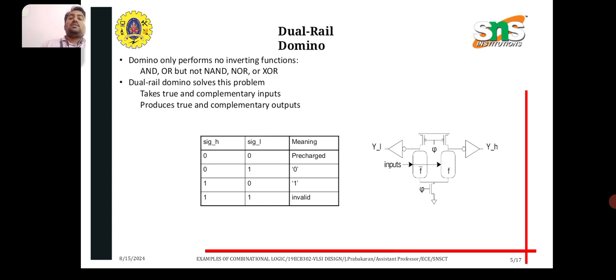Some of the disadvantages of domino logic are static power consumption, charge sharing, and clock dependency. As for applications, we can use domino logic in high-speed arithmetic circuits, processors, and high-performance digital systems.